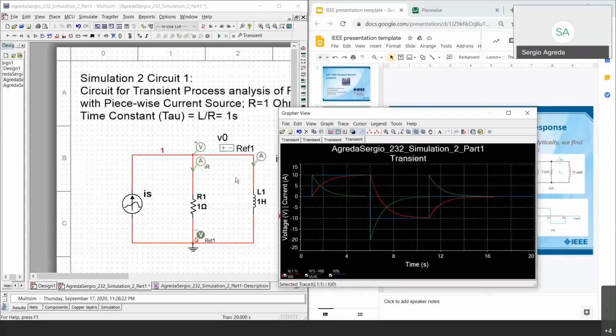Always be careful where you put your probes, because different positions of probes, especially at a common ground, change what you're analyzing. It's convenient that in this circuit all of the main nodes have a common ground. But if you take one node and switch it to here, it's a whole different voltage. Actually, it's 0 because there's no voltage across it.